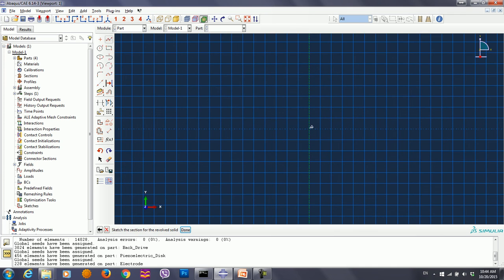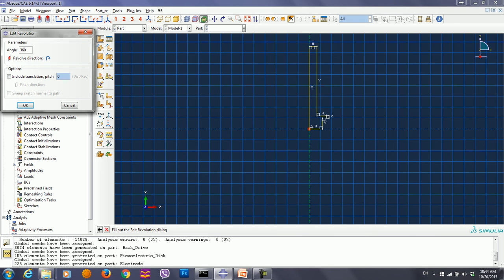Solid element. I use the create lines, the first point 0 and 0, and then 0.012 and 0, and 0.012 and 0.01, and then 0.018 and 0.01, 0.018, 0.012, 0.007, 0.012, 0.007 and 0.0758, and 0 and 0.0758, and the origin. I revolve it 360 degrees.